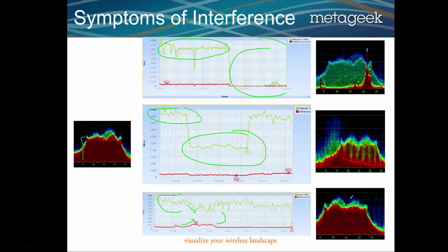Now, a Bluetooth device has 79 channels. It transmits on all of them about 1,600 times a second. So it goes from one to another to another to another and transmits on all of them. This is a technique used by some devices to avoid interference. So if there is something on, let's say, channel 11 like we see here, it will encounter some interference, but it still has room on other channels to transmit on. So it expects to encounter interference like a Wi-Fi network.